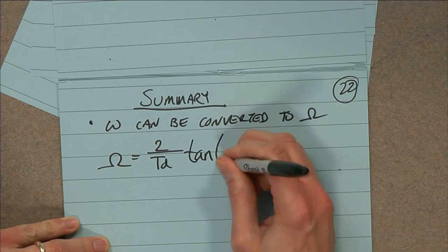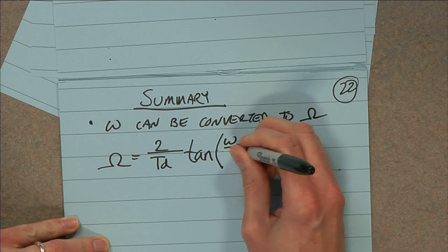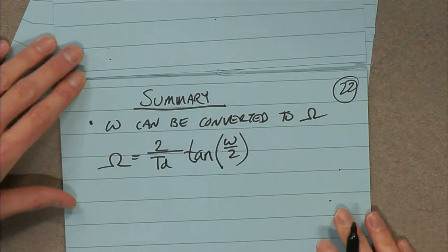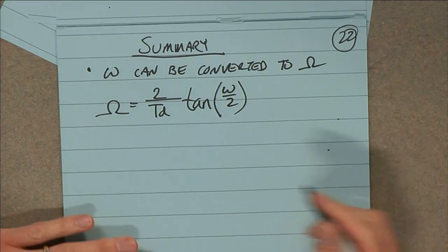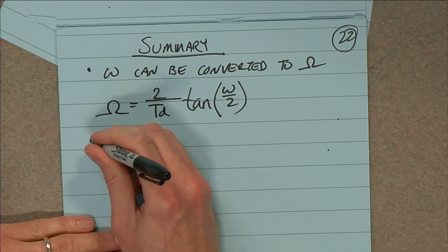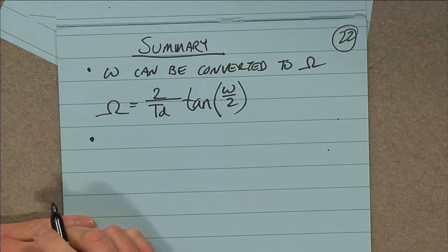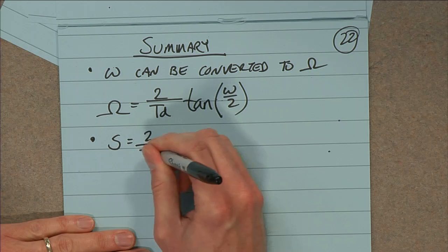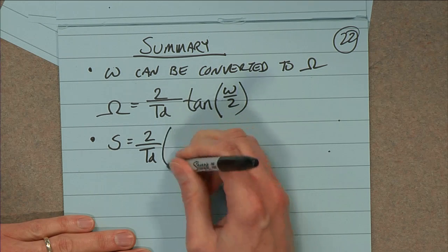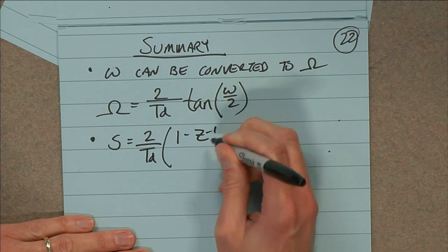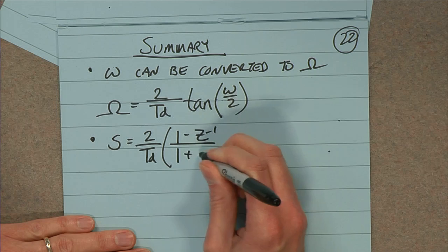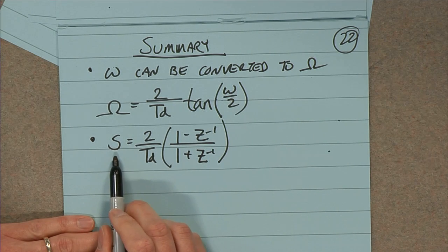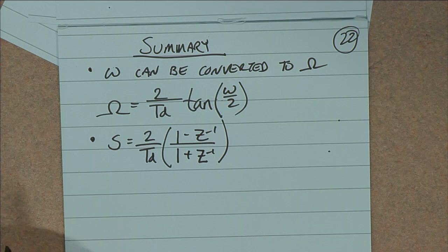We're going to convert frequencies in this domain to this. Then we're going to design the filter. Then we're going to apply the other part of the bilinear transform, where I'm going to use a computer algebra package to help me not mess up all the algebra, because everywhere I see an S in that transfer function, I have to replace it with this mess.